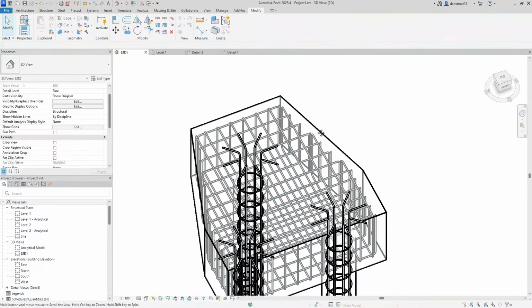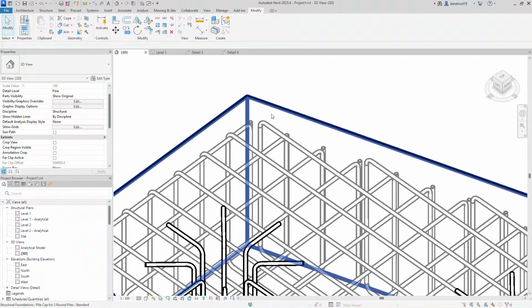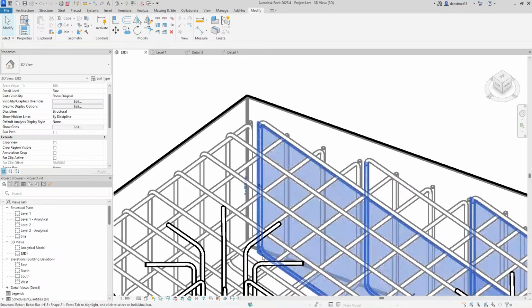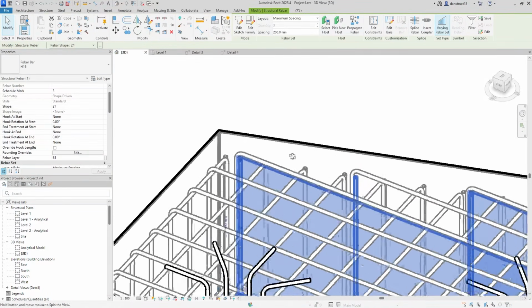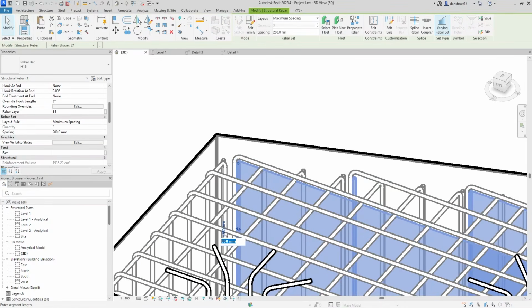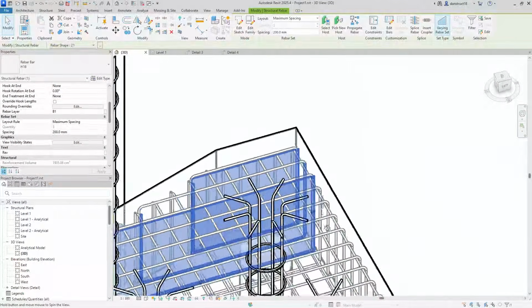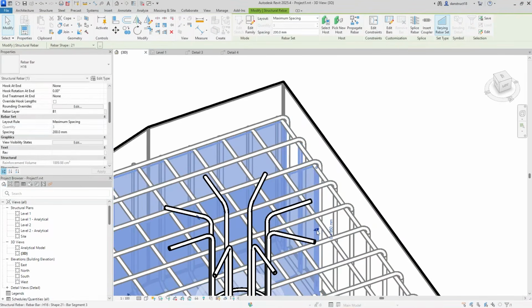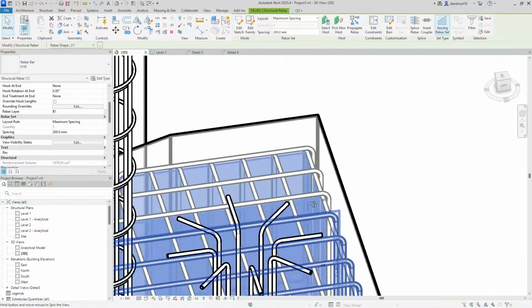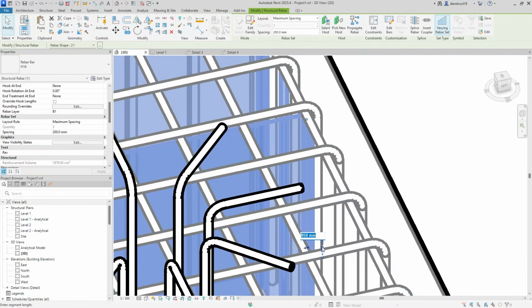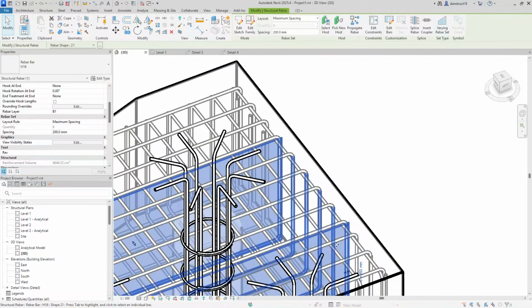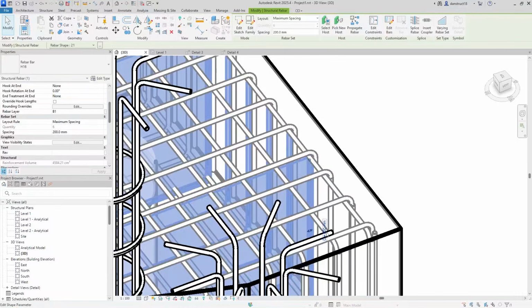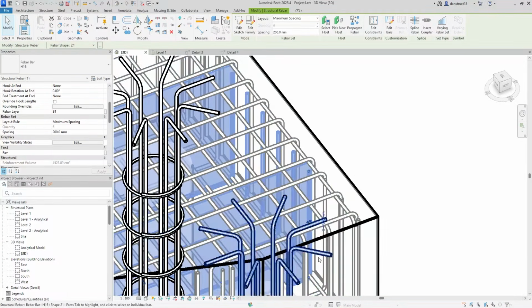All right, good. So we can also look around and make sure that none of these bars are clashing with each other. In this case here, I can see this particular one is too close. So I'll just go ahead and drag it out a bit. There we go. That's much better. We can also change the dimensions. So I can go ahead and change this here to 800, so it's not too close. And I'll also check in this other direction. So this is too close. Just change it here so it doesn't clash with the existing bars. And I'll change the length segment here to 800. There we go. That's just very small steps, but it can be nice if you get them right for fabrication details. So set it here, 800. There we go. All right, good.